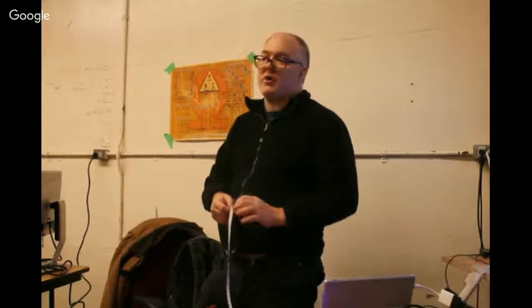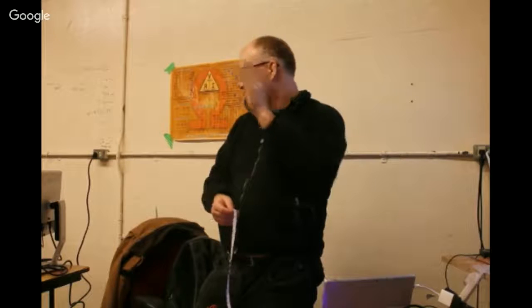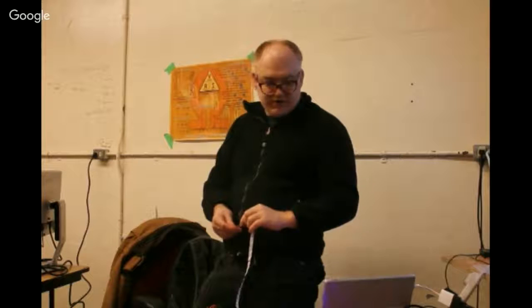As we start talking about motors in another week or two, we're going to be coming back to PWM because that's what you use to control the speed of your motors. In fact, some servo mechanisms also use PWM to control the angle. So PWM is a really useful encoding technique that the Arduino makes pretty simple for us. We don't have to worry about the timing guts to get a PWM signal out. We just have to know it's a PWM controlled output and use the libraries to put that out for us.